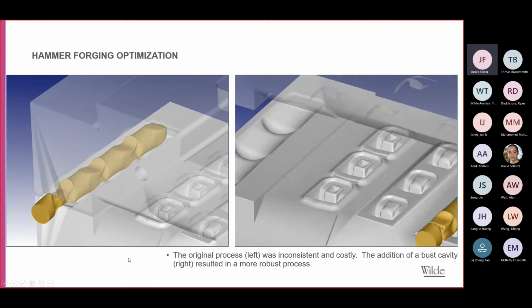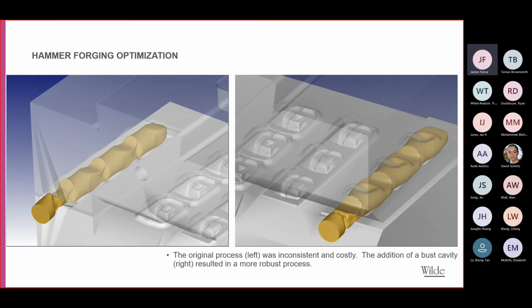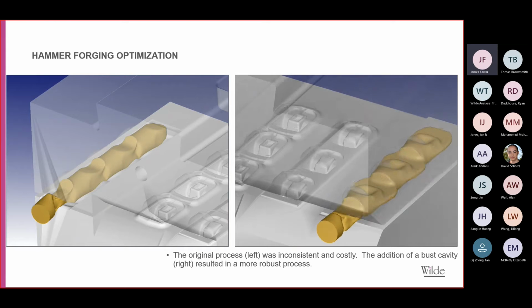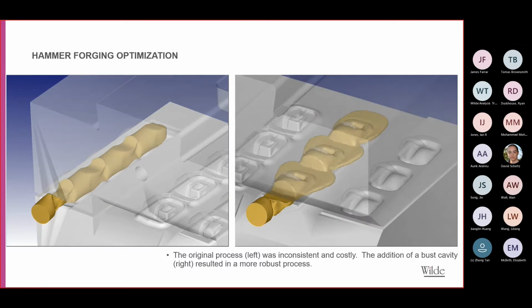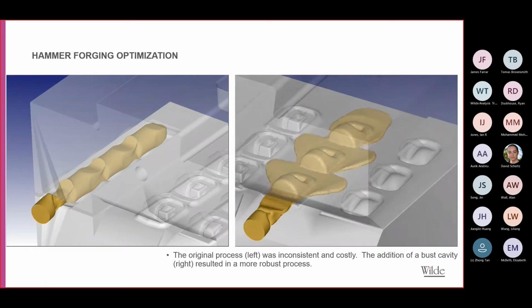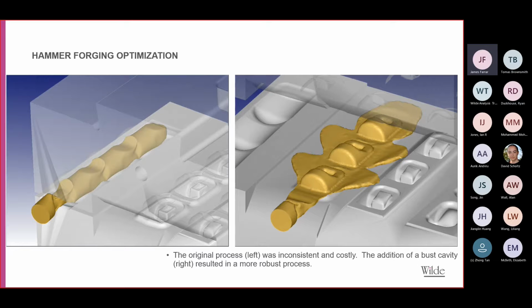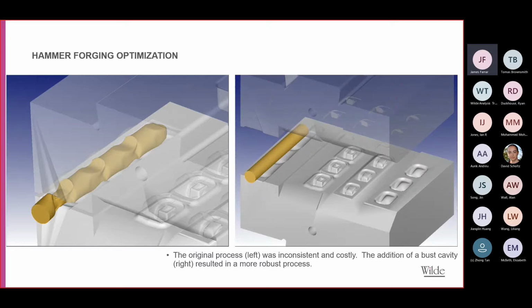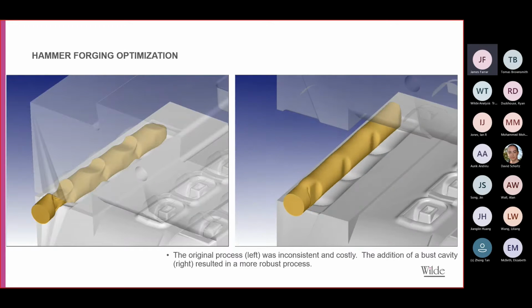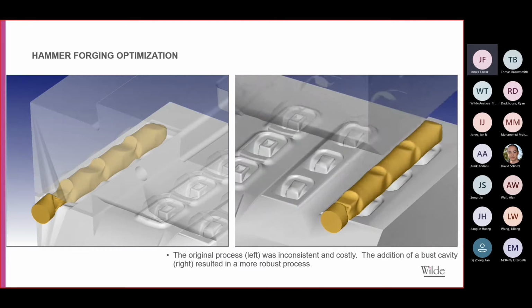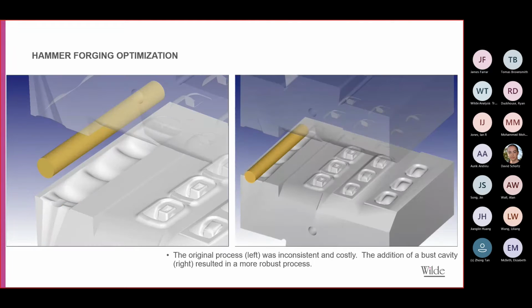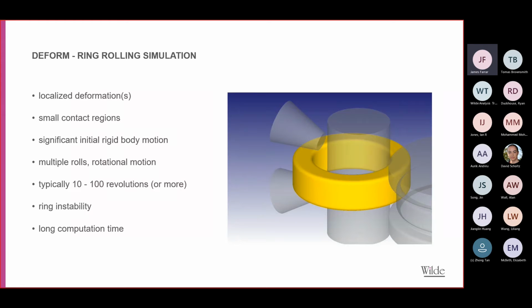So just that initial light one to get it to fit into the main preform. So a much more robust and consistent operation to reduce the scrap. So subtle changes to make a big difference in the overall process. So that's the multi-blow template.